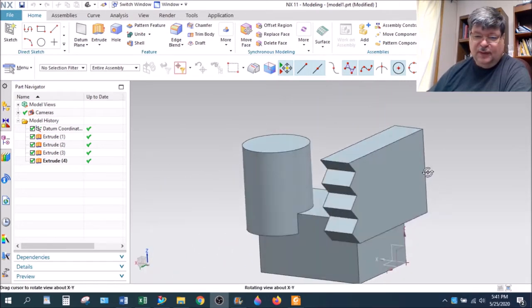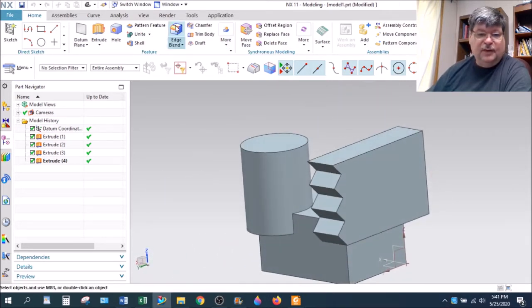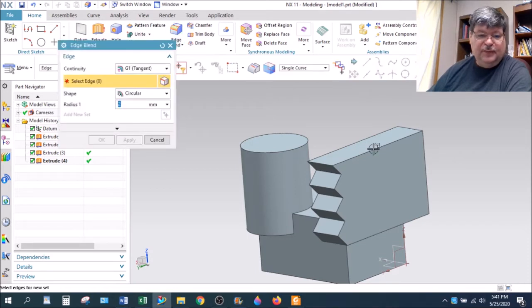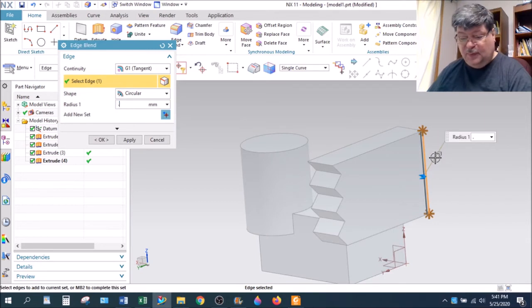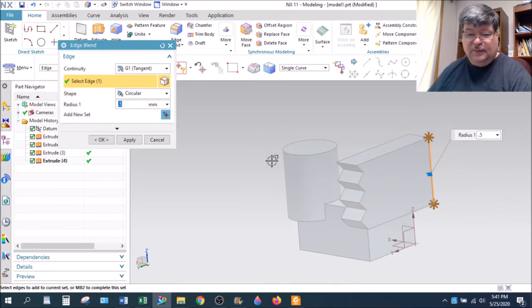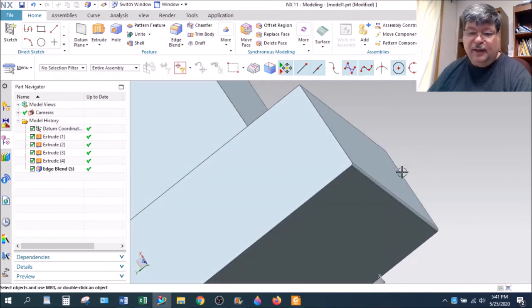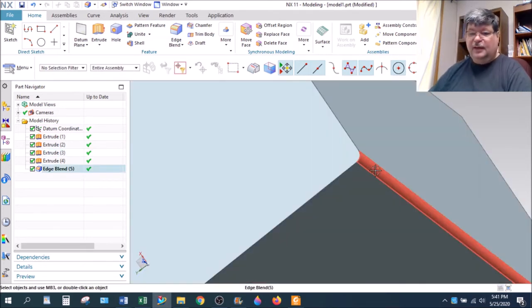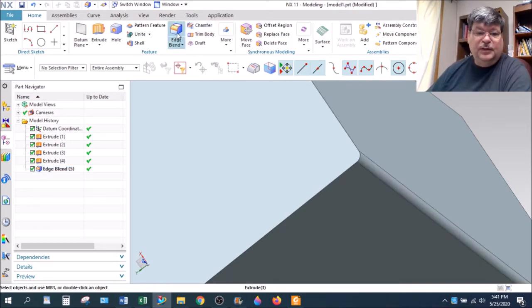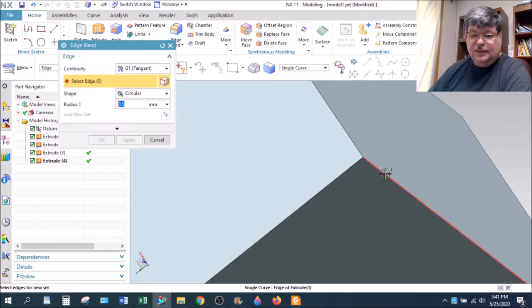Sometimes we think of an edge blend as just a very small rounding of a corner, like here, but it's very small, 0.5. Like the edge of a Lego piece, okay? It isn't really necessarily square. It has just a really tiny rounded edge where the plastic shrunk in the molding or something. Whether you do the edge blend like this, be careful, there's different solutions.